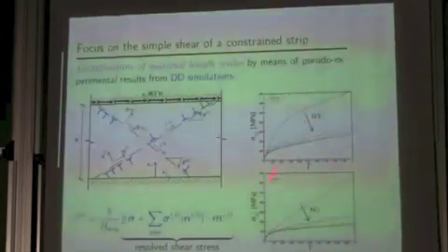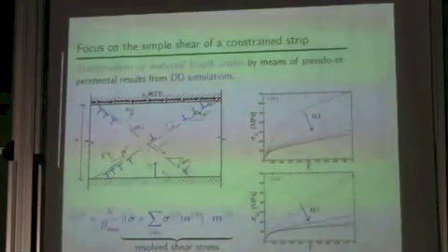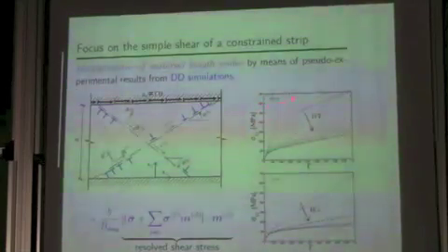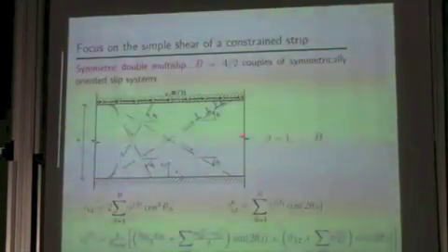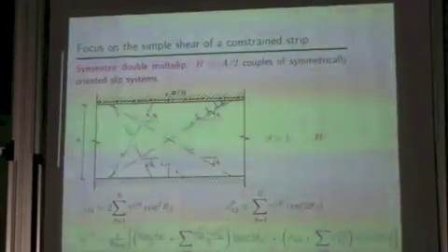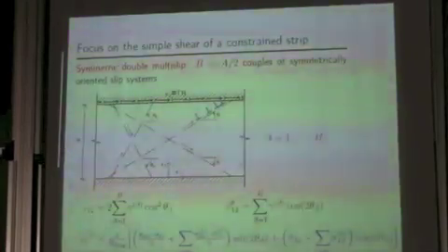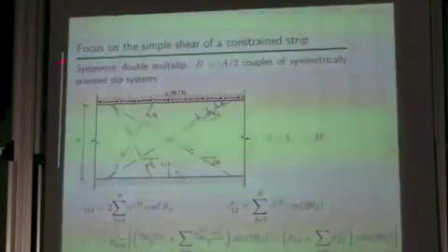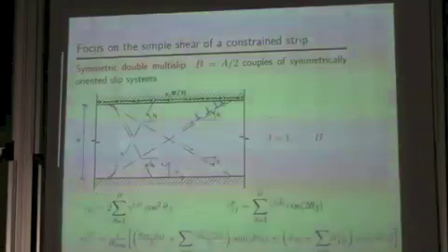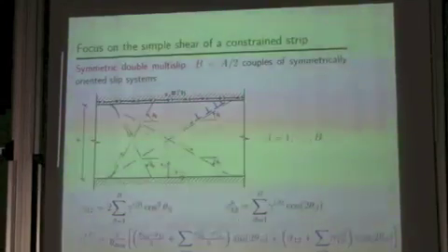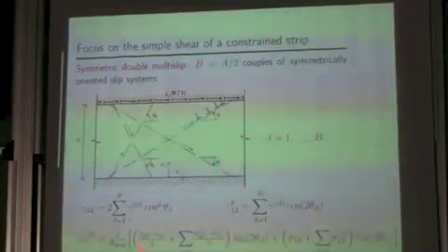Of course, we didn't know which kind of size effects we could find by solving this problem with this dislocation dynamics. This is the reason why here there are question marks. So in order to make things easier, we just consider couples of slip systems symmetrically oriented with respect to the applied shear in such a way that at least in the strain gradient crystal plasticity model, the problem becomes just unidimensional.